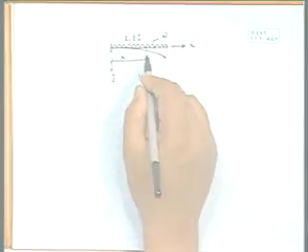So length is L minus x and W is per unit length. So total load will be W into L minus x, and that is in a distributed manner. So moment will be one of the quantities.